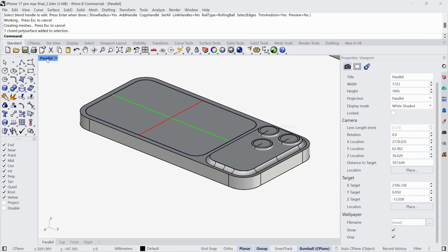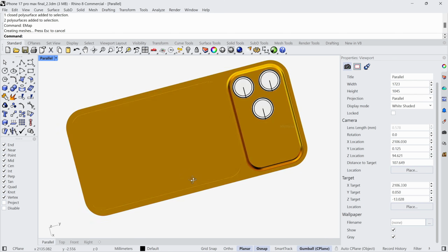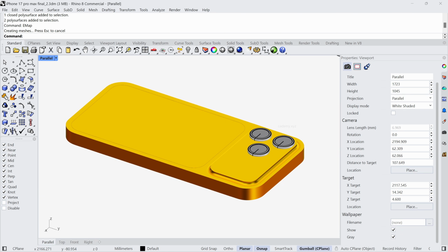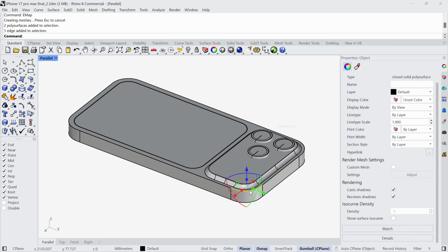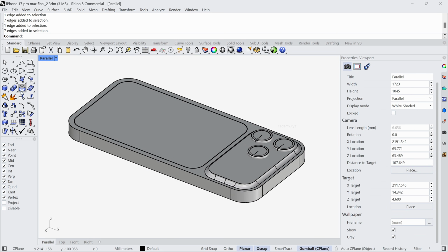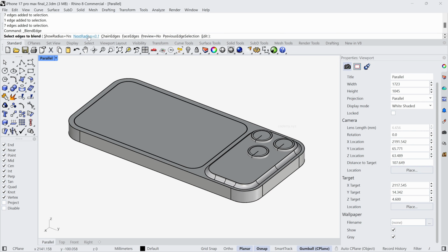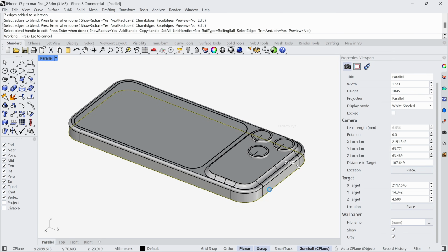You can also look at the end results in the rendered mode or EMAP mode. Let me move these curves and let's run EMAP. So this is how it's going to look like with the micro fillet. Make sure to hide the ISO curves. And finally, we will apply a blend to these boundaries as well. Solid tools, right click blend edge, and we will use a blend of 2 millimeters. Click, double click to chain the edges. Click, double click to chain the edges.